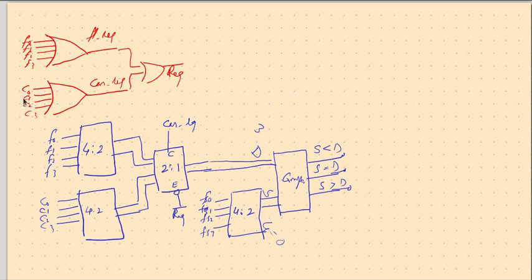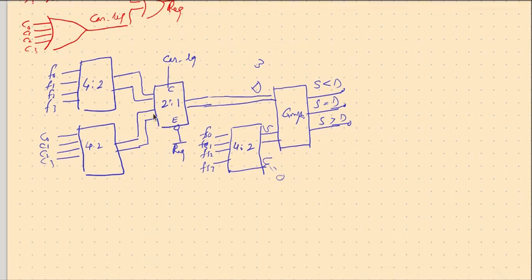So there are four in-car switches to go to the respective floors. So the car request goes high when one of these is hit, or if any of the eight switches is hit, the request input will go high. When none of the inputs is available, the request output will be null or zero.